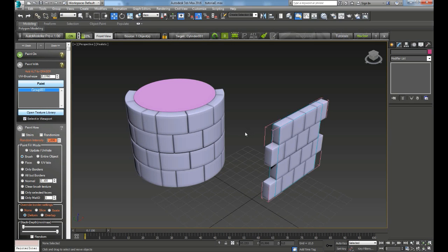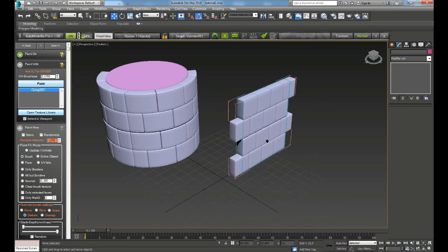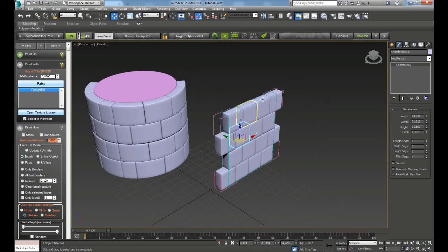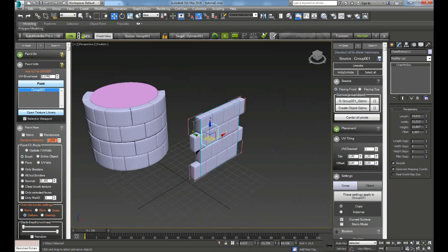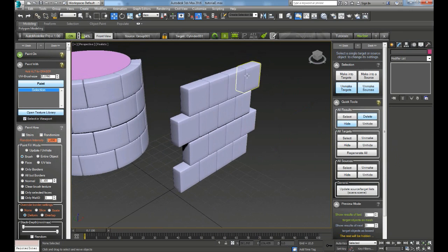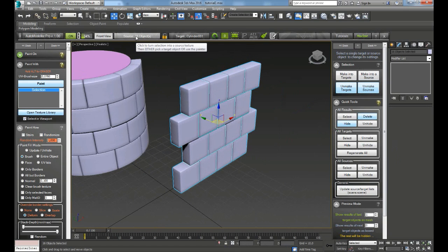One important thing I didn't mention yet, you can unmake an entire source by selecting one object and then select the property window and click on unmake. This will remove all AutoModeller data from the source and remove the gizmo object, and then you can apply changes to it or add new objects and remake the source again.